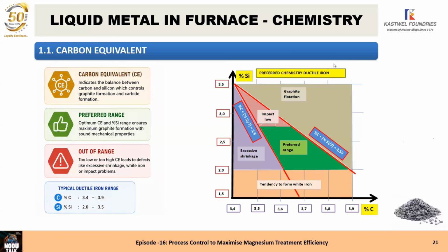I have used this process in one foundry for making small castings of weight 2.5 to 3 kilos, two castings per mold. It ran for about 2 years, and then there was so much buildup of returns that we had to sell the returns. Comparing all these processes, the sandwich method generates more pollution.